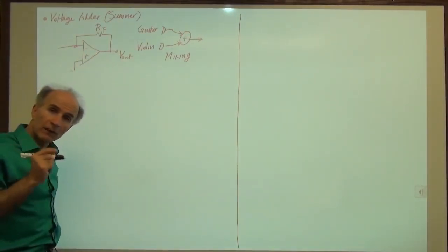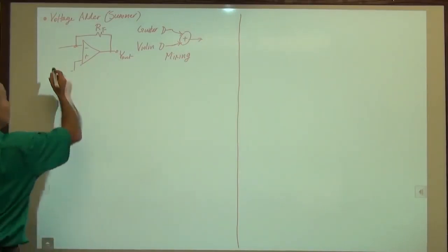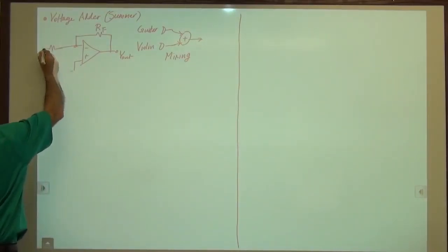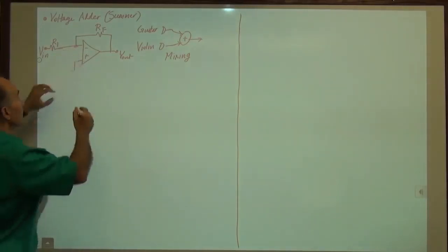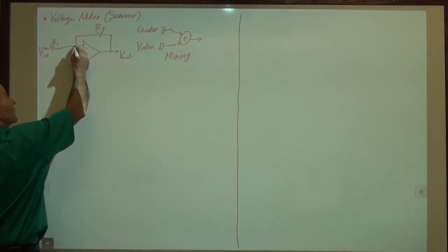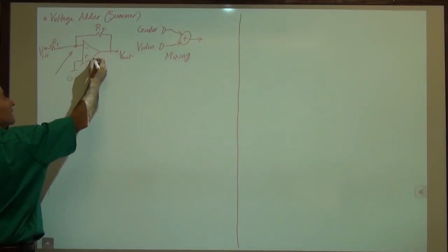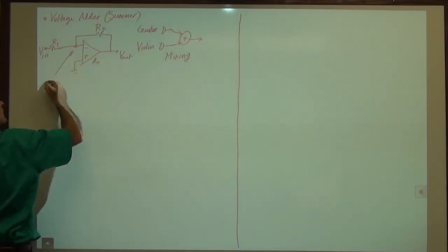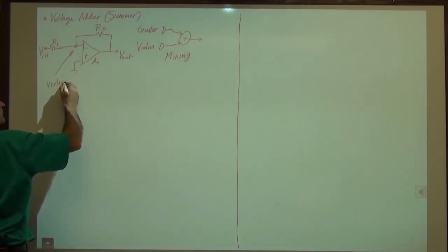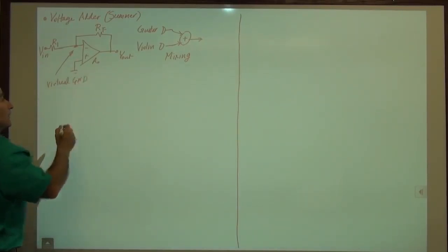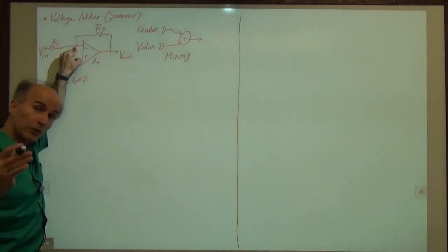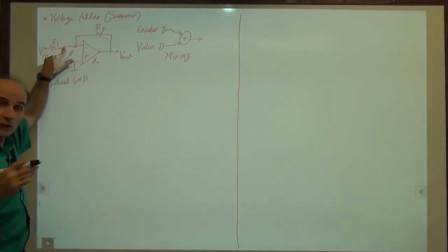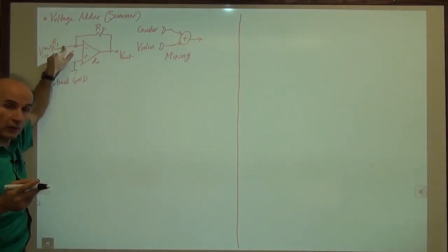Now what I remember from the inverting amplifier topology is that if I have a resistor here and I apply a voltage here, then by the effect of this virtual ground here, if A0 is large, so this is virtual ground, right? We said, due to this virtual ground, this voltage is close to 0 and doesn't change much, which means the current through R1, to a good approximation, is just V in over R1.